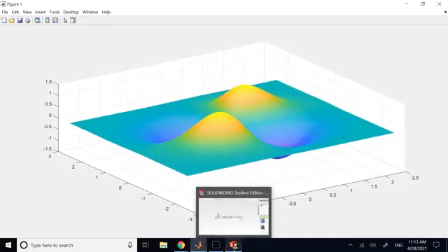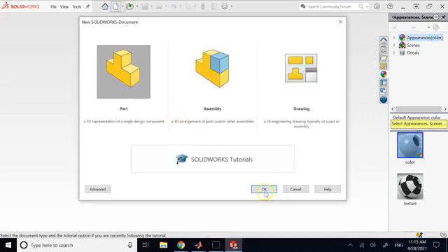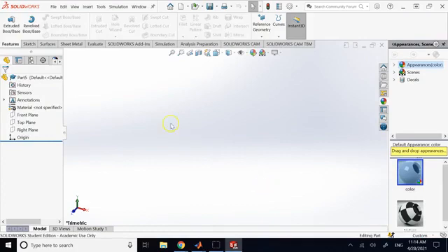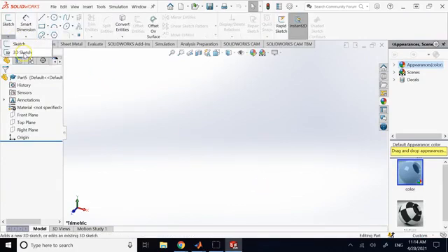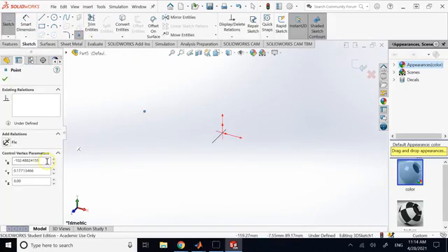And well, if you have worked with SolidWorks and CATIA, you know that they have some functionality for this, but they are not really going to make it easy for you, because if you want to do anything like that in SolidWorks, for example, what you need to do is to go and create sketches, and you need to go to 3D sketches, and then in 3D sketches, once you create an x and y for a point, then the z for that point, so you see here I'm clicking somewhere x and y, then you have to make this z a function of x and y, and that only gives you 1 point. Correct? And then you need another point, another point, another point. In all of those points, you make z to be a function of x and y.